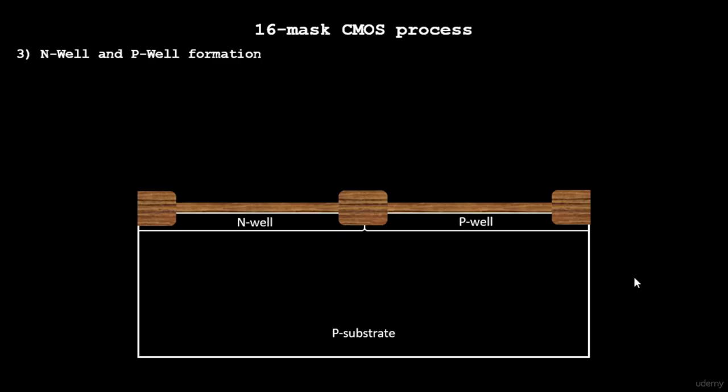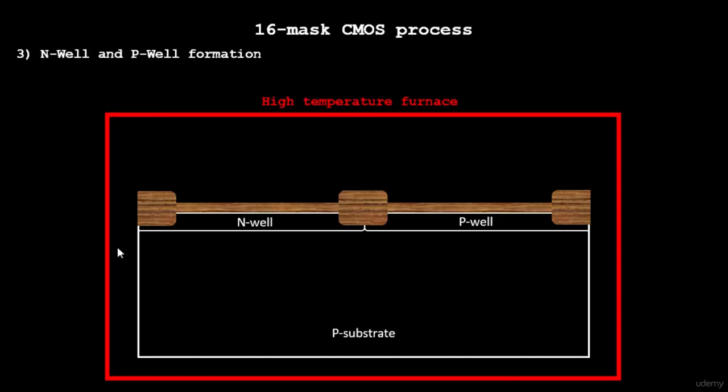So this is how you protect your two different transistors from communicating with each other. The next step is to remove the silicon nitride, or etch out the silicon nitride, or strip it out in a hot phosphoric acid. Okay, so this is how you get your isolation region.